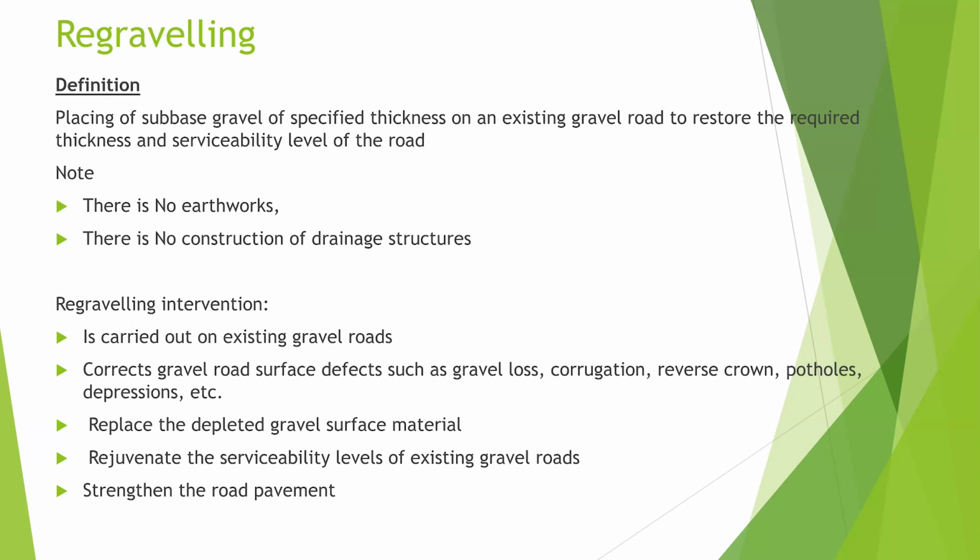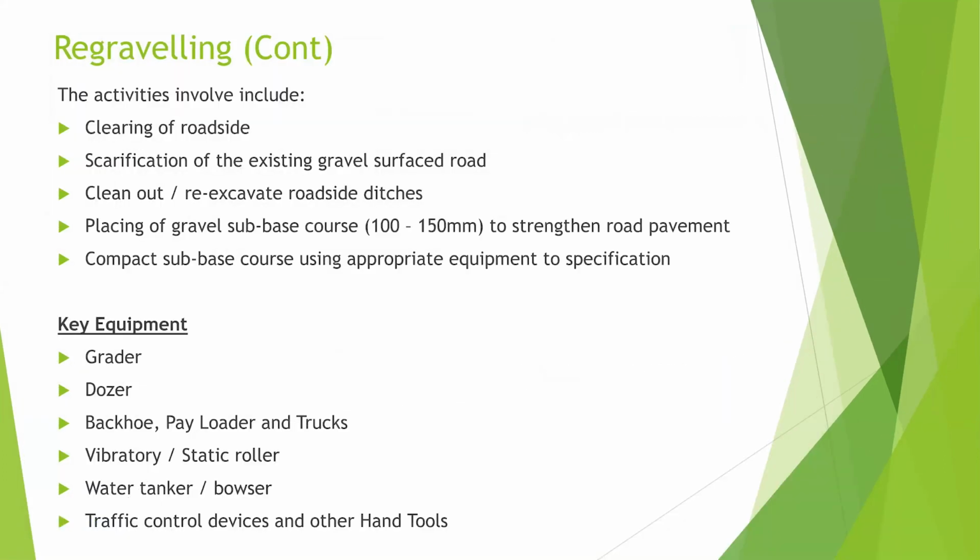The intervention is supposed to replace the depleted gravel surface material and also rejuvenate the serviceability level of the existing gravel roads and strengthen the road pavement. Now, the activities involve roadside clearance, scarification, the clean out or re-excavation of the roadside ditches, and most importantly, placing of the gravel sub-base material, usually between 100 to 150 millimeter thick, to strengthen the road pavement. You compact the sub-base using the appropriate compactive equipment to specification.